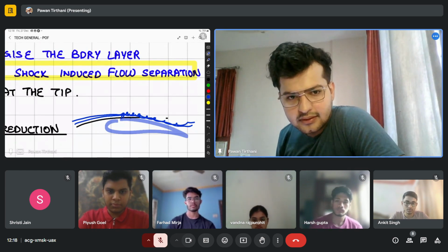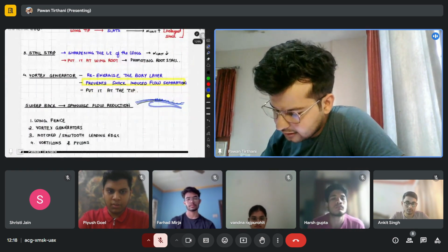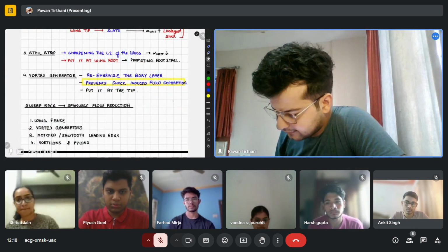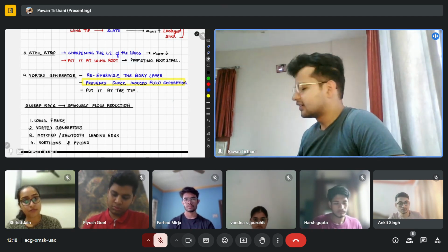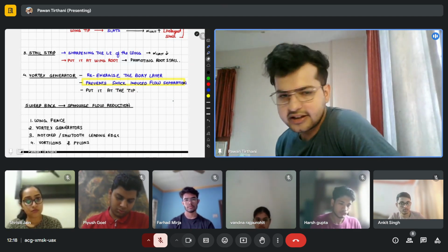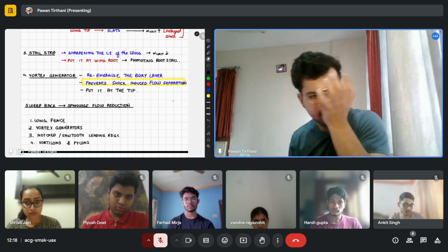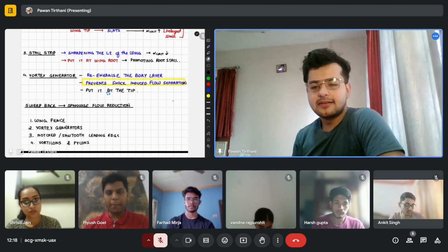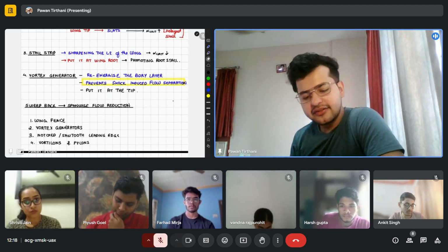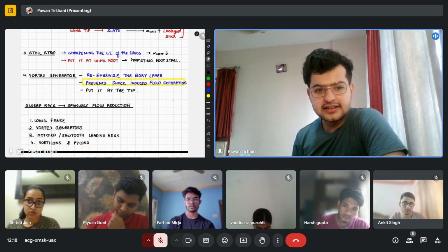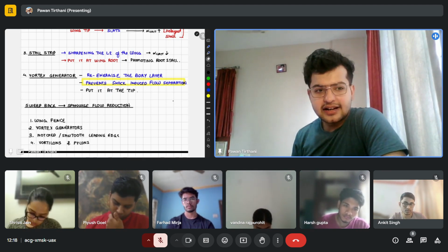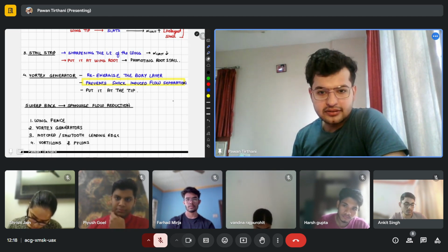Okay. One more thing, please note it down. Whenever you solve questions, you will always get confused between the words regenerate and re-energize the boundary layer. A vortex generator can never regenerate a boundary layer. Only a slat or a slot can regenerate a boundary layer. But a slat or a slot can also re-energize a boundary layer.